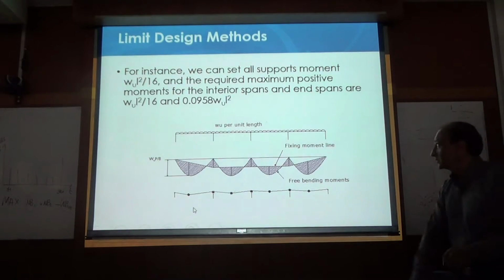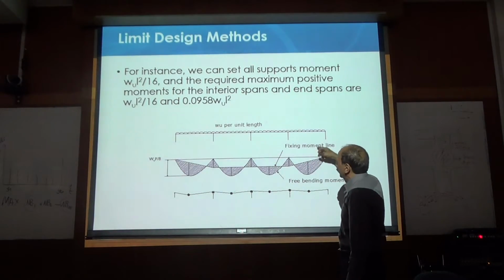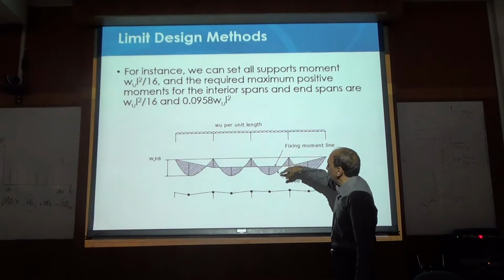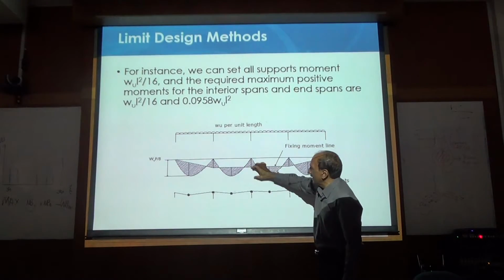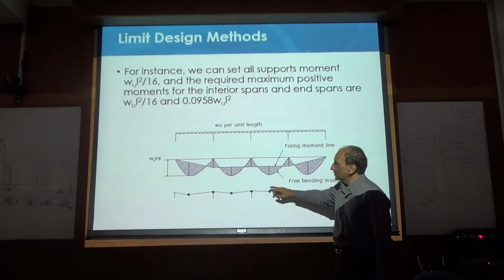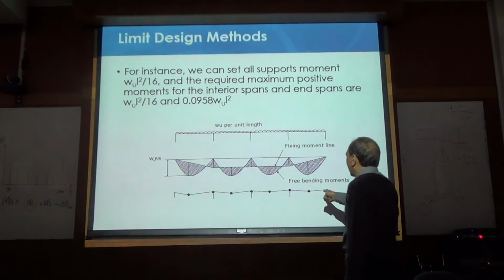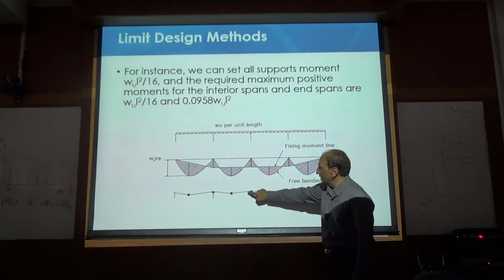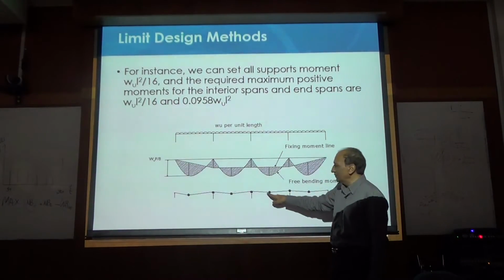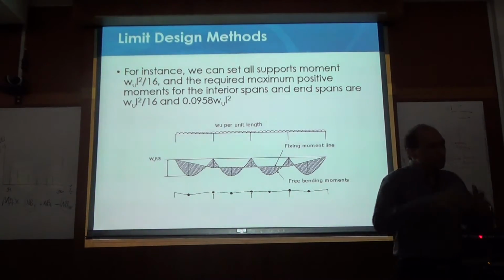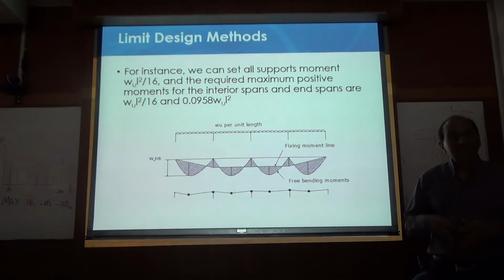So this is what we are talking about. You have a bending moment, you have a beam like your beam, and you get these bending moments, negative, positive, and then you can move them up and down this moment diagram in such a way that you can control the bending by yourself by putting hinges, and that is what you are doing. Your beam is like this, one span of this beam. So you have 3 hinges, 1, 2, 3. You are going to control these hinges to control the bending moments, and redistribute them as you want. So in your case, positive moment is larger than negative moment, correct?